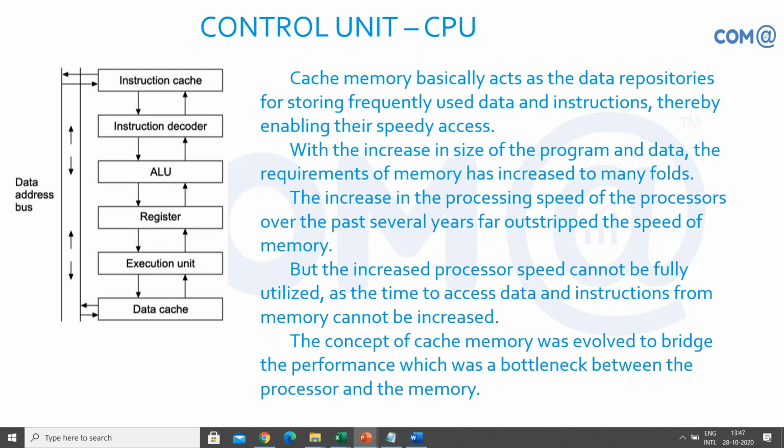And one more thing here is, even though you have a good processor and memory, if you don't have a good address bus, that is the FSB, front side bus, which is on the motherboard, with high frequency and high clock speed, then there is no use of having a high-end processor and memory. So we need to have proper motherboard design so that it can transfer more data from your processor to cache memory or processor to normal memory, whatever it is. So this plays a very important role.